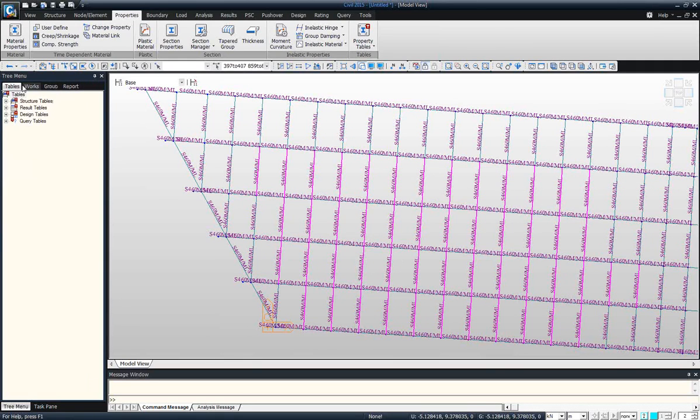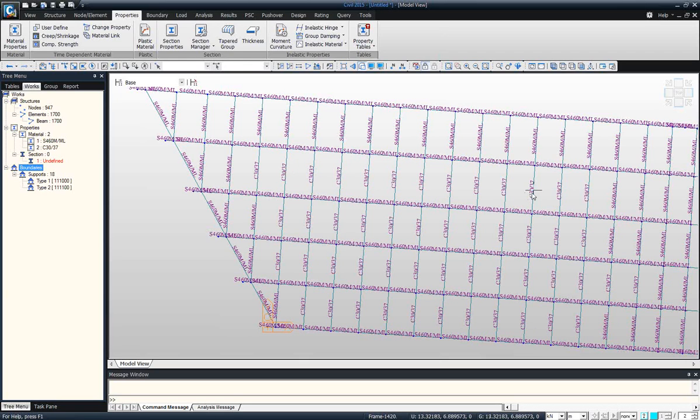Close, and then we go to works, and here we have our list of materials. We choose concrete, and we use the so-called drag and drop function, and we have our element changed. The same thing we can do when we have section property, which I will show later.